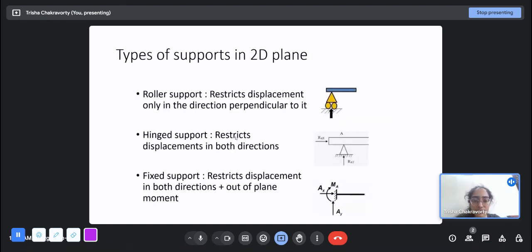These are the kinds of supports. Now obviously a structure is under some kind of loading, it also needs to have some support, otherwise it will be unstable, right? If I put a force on this phone, it will fall down. Till it has a support, it will not be stable, it will keep moving, and that is something we cannot allow. So we need to secure a structure with boundary conditions or supports. There are three main kinds of support, I mean, three idealizations. Again, these exact kinds of supports are not available in the real world, but these are idealizations of certain kinds of support.